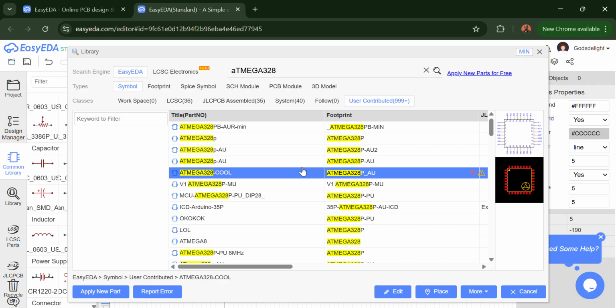So these are components people wanted to use in designs. They had a variant that was not listed on LCSC and they created a package for that component and used it in their design. It was not placed on that board because that component does not exist in LCSC stock. So they got the board without the components, ordered them from a totally different supplier, and placed them on the board. You can create your own custom components and use the same method if need be.